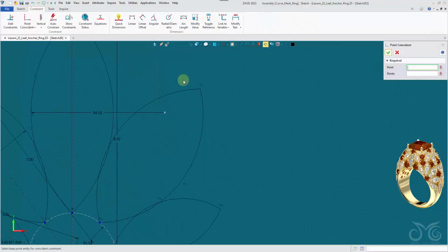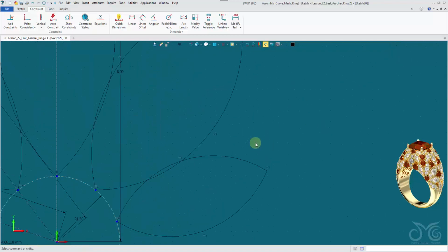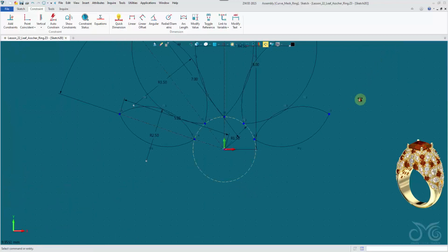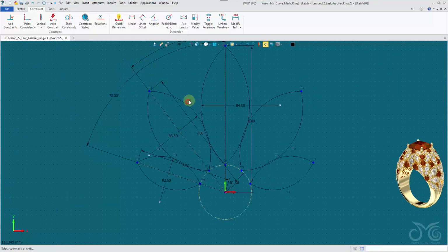Point coincident constraints, going to constrain the two endpoints to stay attached to one another, so when that happens we should see a blue dot thrown in, like this blue dot here. So to do this coincident constraint, because they're already touching, I'm going to grab the points by coming on to each line. There we go. Middle click. Okay, they're linked up now.